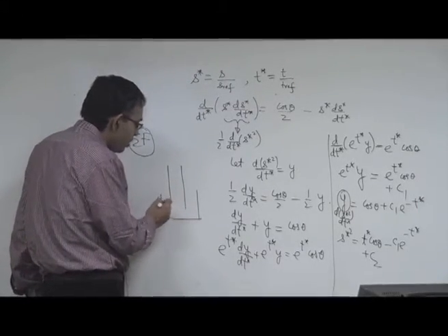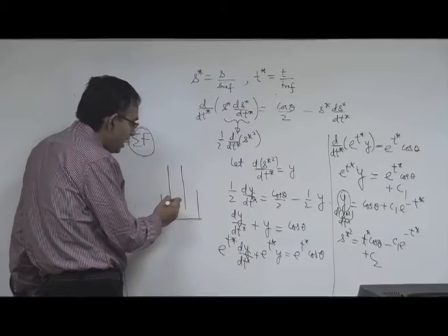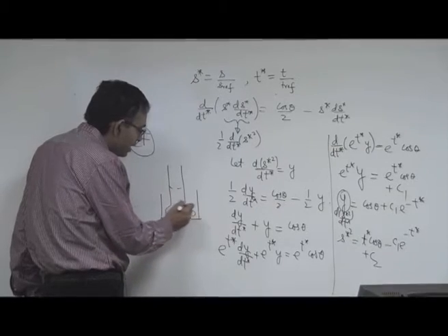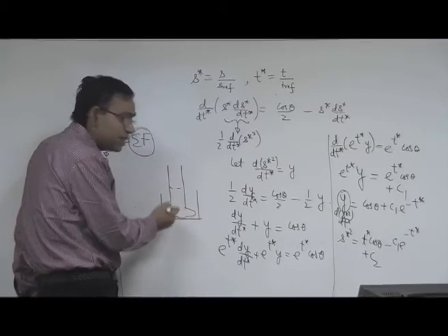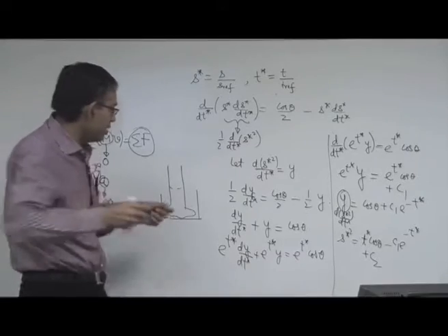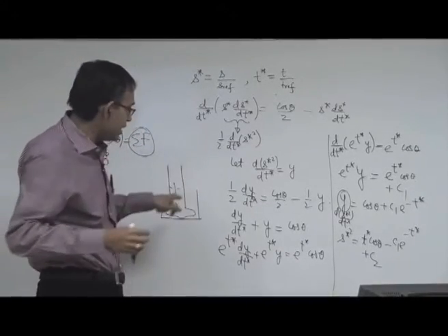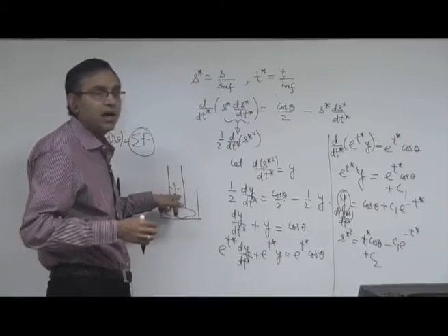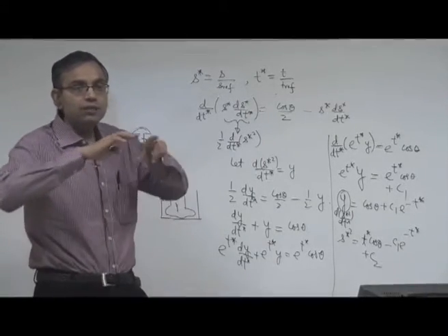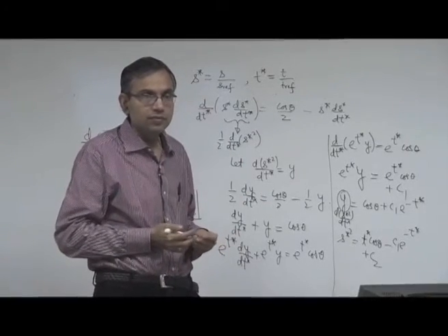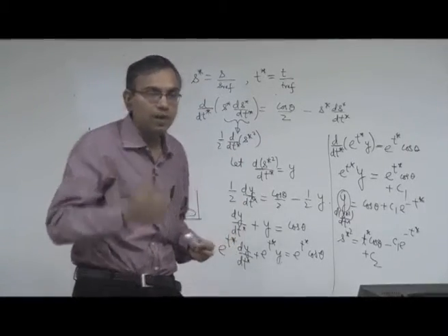We are not showing what is there in the reservoir. Ideally, whatever is in the capillary forms a connected system, and there is an additional mass which is also sucked up when this fluid is moving. That additional mass, together with the mass in the capillary, actually forms a control mass system, not just the mass within the capillary.